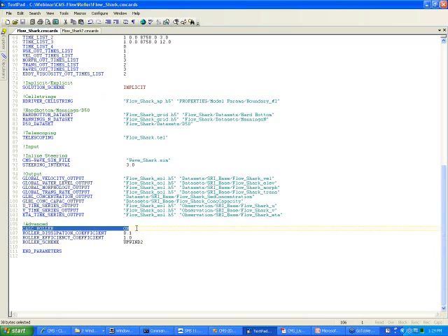In this case, I was not using the wave average formulation. I just turned on the surface roller, and then I gave the roller dissipation coefficient and the roller efficiency coefficient. This roller scheme refers to the transport scheme, and the options are a first order upwind scheme, a second order upwind scheme, and the Lax-Wendroff scheme. And those options are described